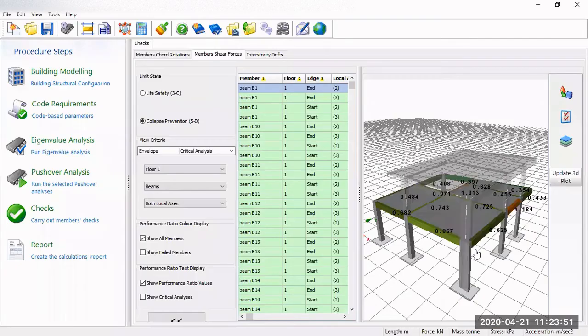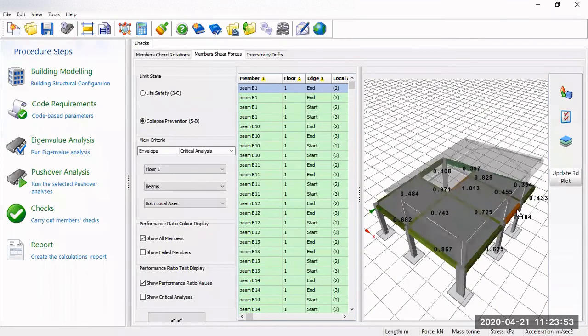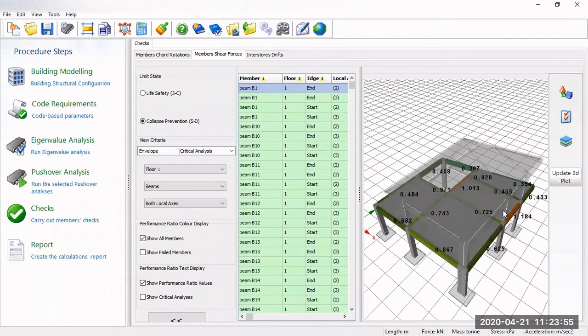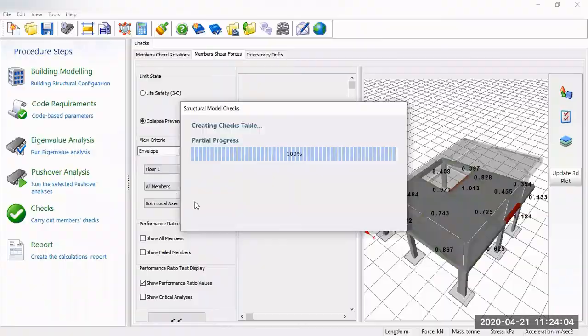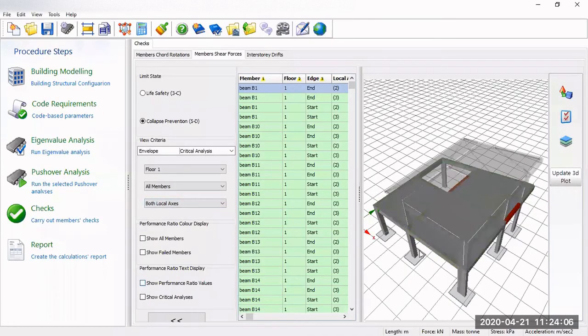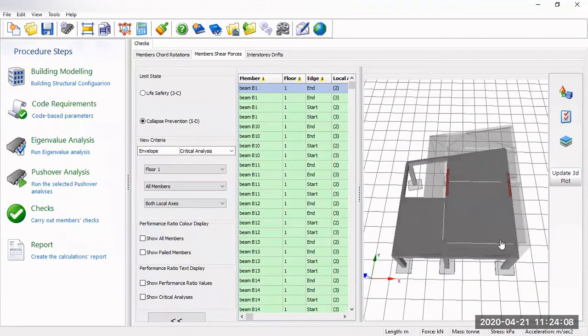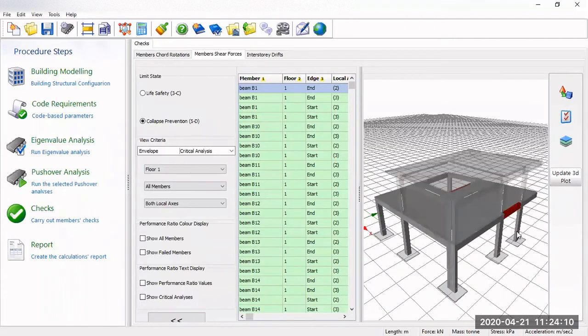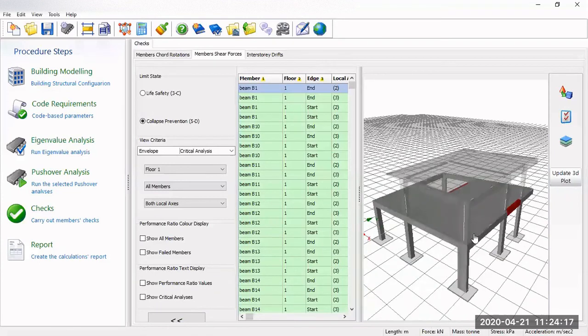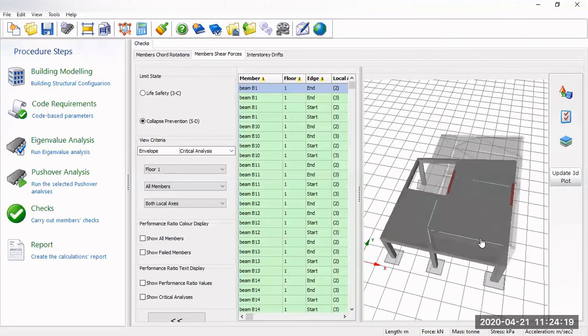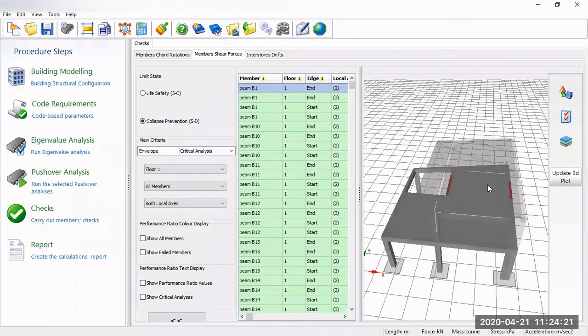All right, it looks like for two of the beams the value ratios are more than 1. So it's showing some values. We can maybe select here, choose all the members. You see more clearly without the values. So from this exercise, we notice that for beam shear, these two beams seem to be failing in shear. It's something that we want to prevent, shear failure from happening.